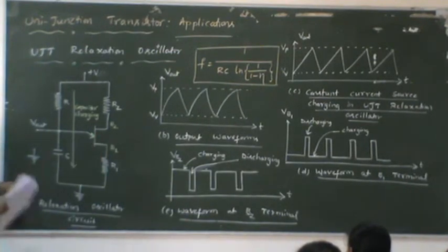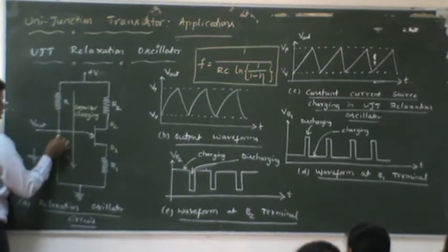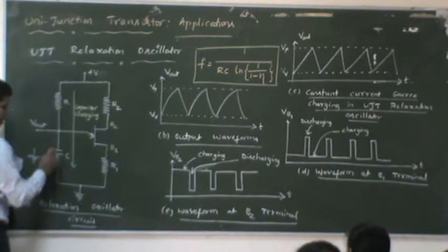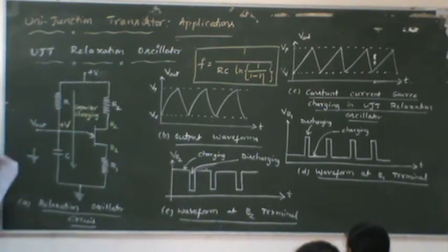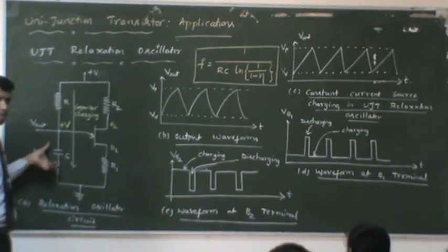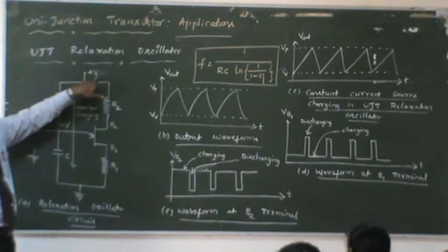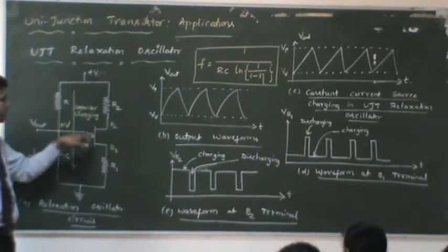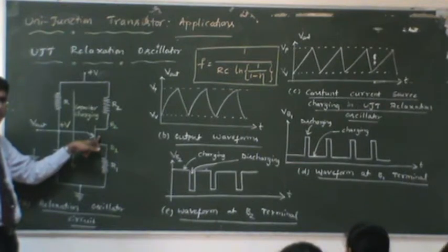So look at here now. Once this capacitor gets charging, let's assume that it charges to the supply voltage. Voltage across the capacitor, between this point and the ground, becomes, say for example, plus V. Let's assume a situation in which the capacitor has acquired a sufficient amount of charge, and the voltage has now become plus V, which is the same as this. Now what will be the condition inside the diode present here? Do you think it remains reverse biased?